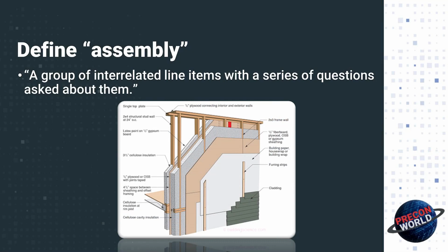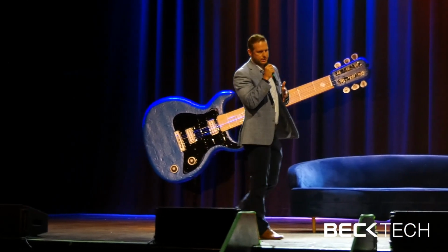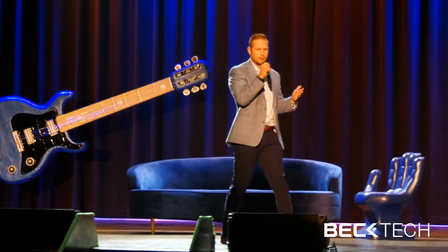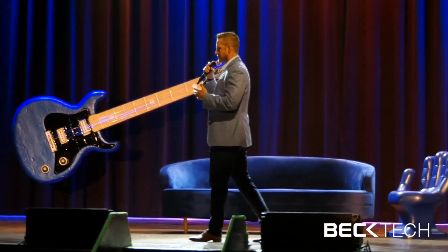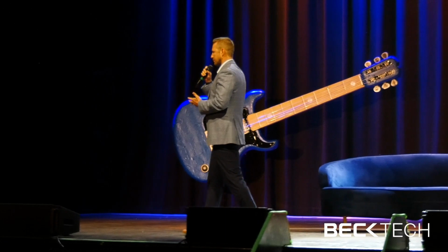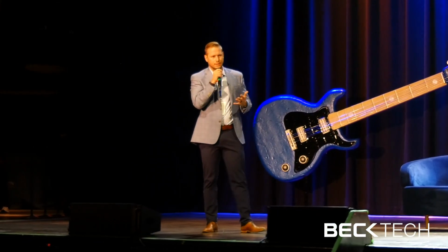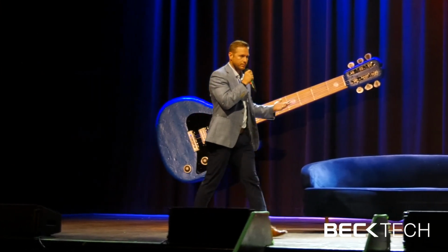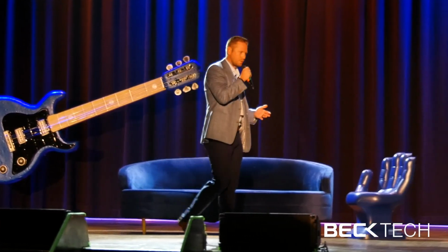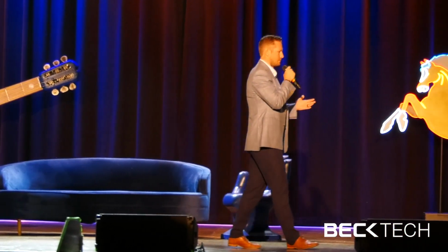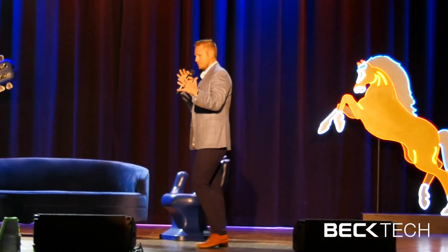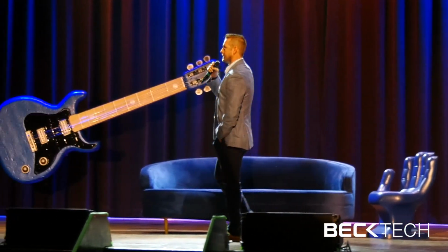So in this case, up on the screen is an exterior wall assembly. You could have, what is the exterior skin? It's stucco, it's metal panel, it's brick veneer. Okay, what's on the back side of that? Is it rigid insulation, spray applied insulation? Is there fluid applied air barrier, Tyvek? What's the framing behind that? Is it stick framed? Is it steel framed? What's the cavity insulation in there? Is it batt insulation? Is it spray foam insulation? And then what's on the finish side of that? Is it gypboard? Maybe there's plywood in some instances. Maybe there's wall covering. All that makes up an assembly, right? So I think we're all on the same page of what that is.